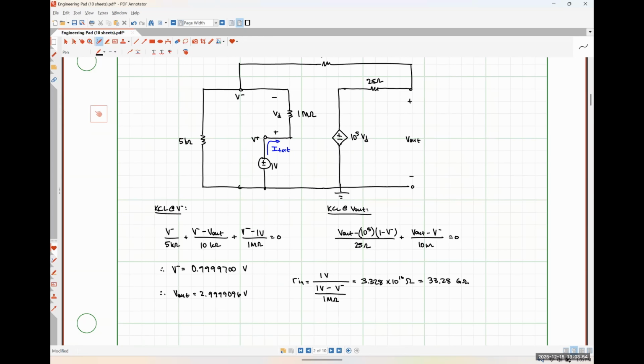But anyway, one of the properties of negative feedback is that we can use it to actually manipulate the input resistance and the output resistance of our system. So in this particular case, we have an increase in the input resistance. What we'll see, based on the configuration of our feedback network, is that we're also going to have a pretty large reduction in our output resistance, which again is really, really good because we're doing voltage amplification here.